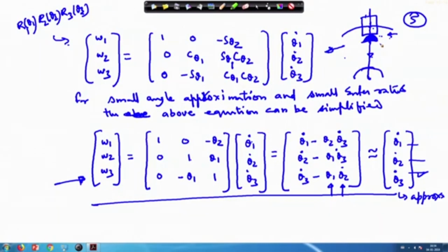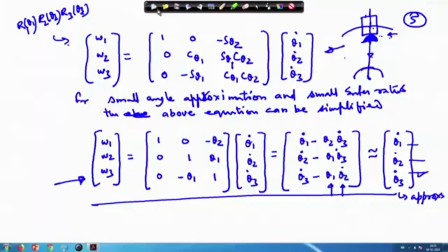Earlier we have also observed that rotation about the minor axis is not stable if internal energy dissipation is taking place. Obviously, you have a satellite, so there may be some vibration, it is not a perfect rigid body. So, there will always be some vibration involved with the system, and energy will start dissipating. So, we have to look at whether the satellite is stable or not, and under what condition it will be stable. This is what we are going to work out here.